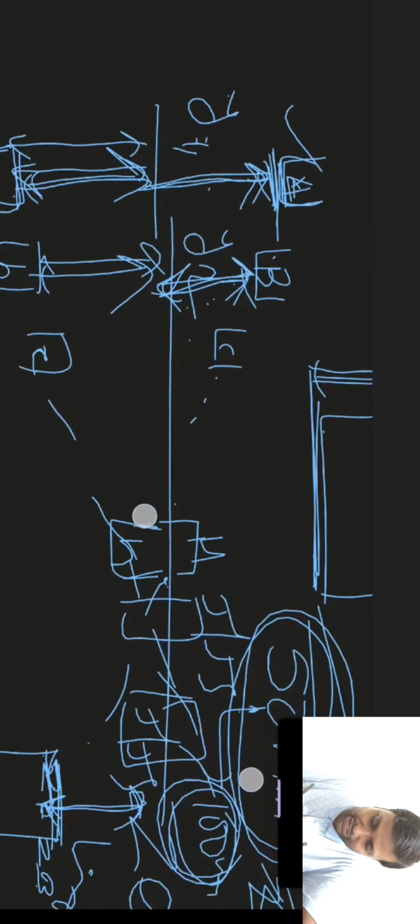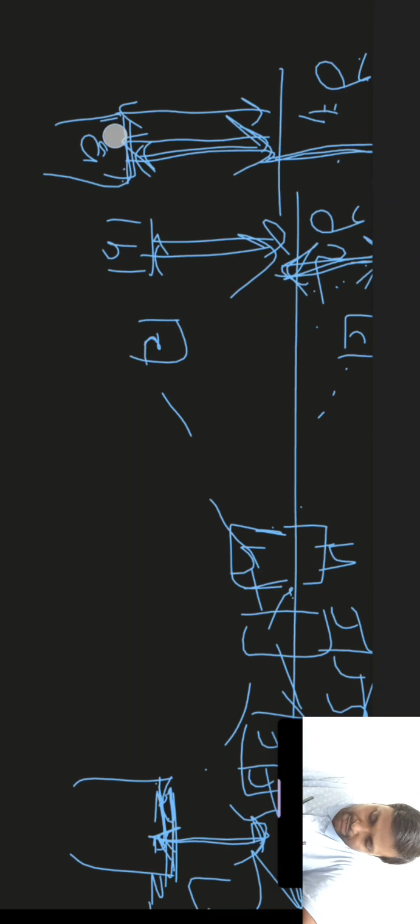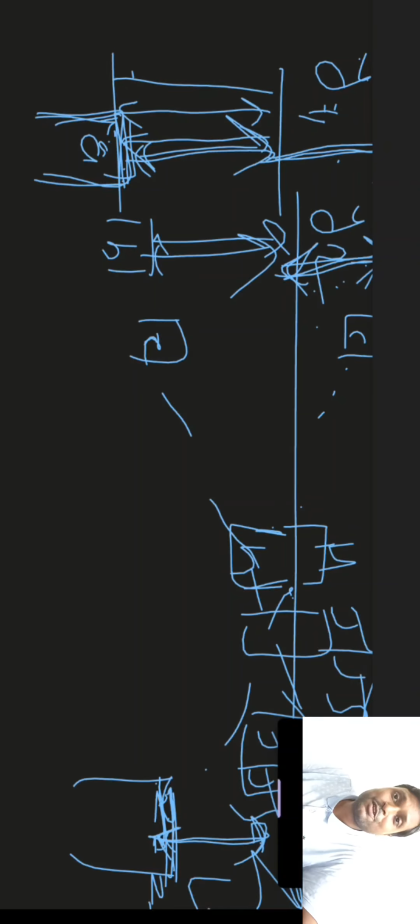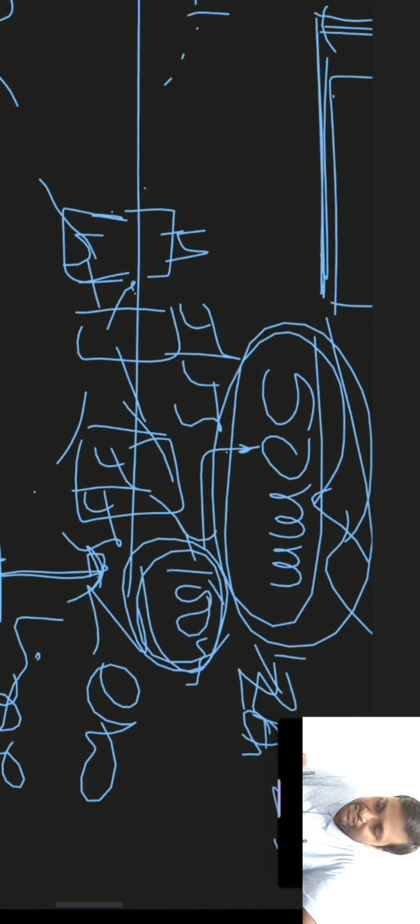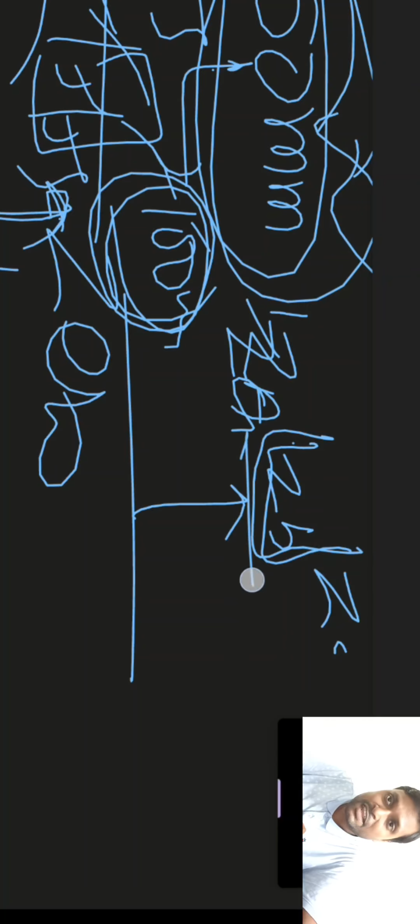So for the shaft, the fundamental deviation of A is nothing but the écart supérieur, since it is below the zero line. And for shafts such as ZA, or you can say ZB, the fundamental deviation will be nothing but the minimum, or you can say lower deviation, and lower deviation means this is écart inférieur. We will shortly discuss the sign.